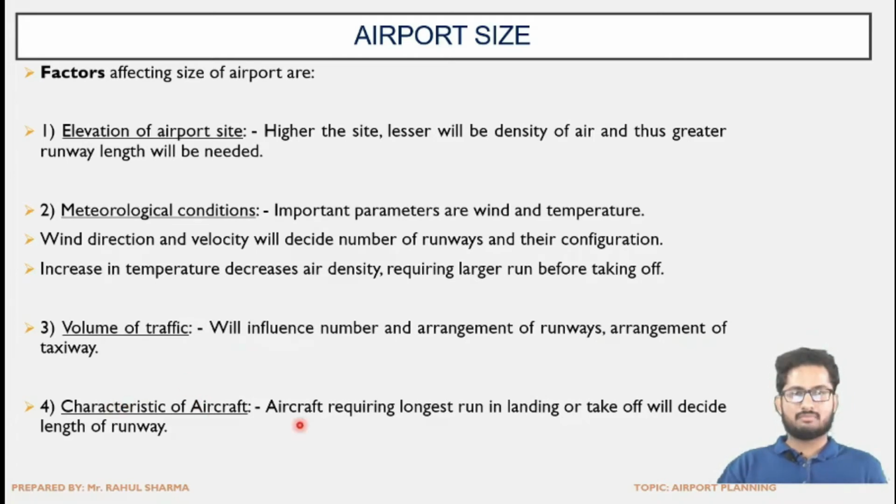Characteristic of aircraft, that is, the aircraft requiring the longest run in landing or takeoff will decide the length of the runway. If at an airport various types of aircraft are to be handled, then the one which requires the longest run at the time of landing or takeoff will ultimately determine the length of the runway, and depending upon it, the size of the airport will be influenced.